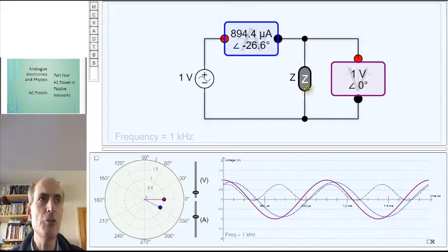But just occasionally, at one point in the cycle there, the instantaneous power goes negative, which means this component is returning energy back to the circuit just for this short amount of time between the zero crossing of the voltage and the zero crossing of the current.